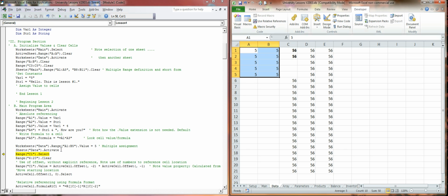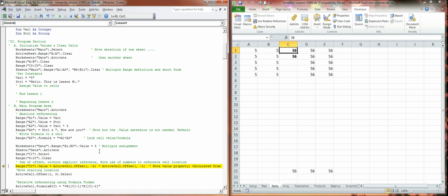All right. Next one, we've been dealing with columns before. I just wanted to show you that we can actually deal in rows as well. So now we're going to say on this particular worksheet, we don't have to repeat which worksheet we're on. It's going to assume that we're on the same worksheet. We're going to now do an operation on a set of rows everywhere from row 6 to 20. And if we hit the F8 key now, all right, everything from row 6 to 20 has been erased.